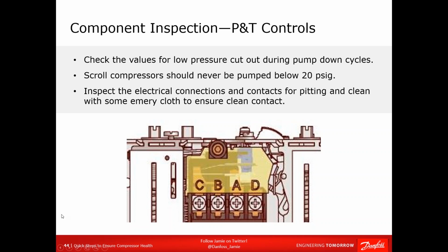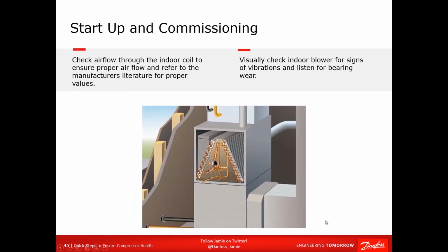They should not stick. And if you see sticking or you see some black oxide burning on there, all right, clean them or replace the control, or during preventive maintenance, clean the contacts with a little bit of emery cloth. You can pull this cover off as well as see through it, clean them up, dry them out, and put it back in there. It's a great fix to keep the system going.